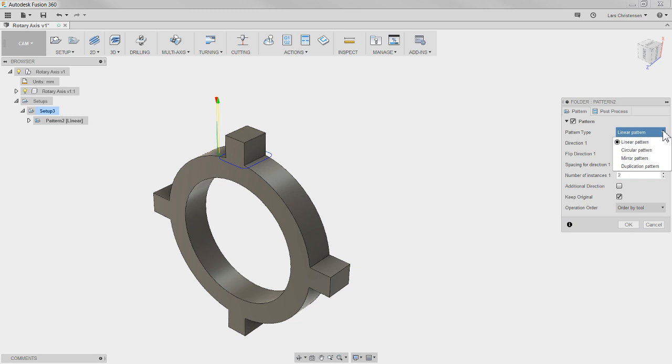Just to answer quickly one question in here, this contour selection that I'm doing right now with the open contour is not just for Ultimate. That works in all of it. The only thing that is Ultimate here is if you want to do simultaneous machining with your fourth axis, which we're going to get to a little later.